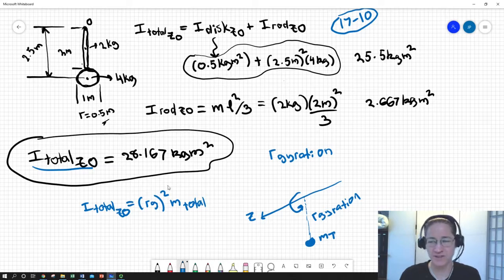A uniform material change might be the only thing that did that. So all we would end up changing is the radius of gyration. So we can basically adjust our total moment of inertia with changing mass, and we're using a single number to describe the result of all of this integration of distribution of that mass about our axis of interest.